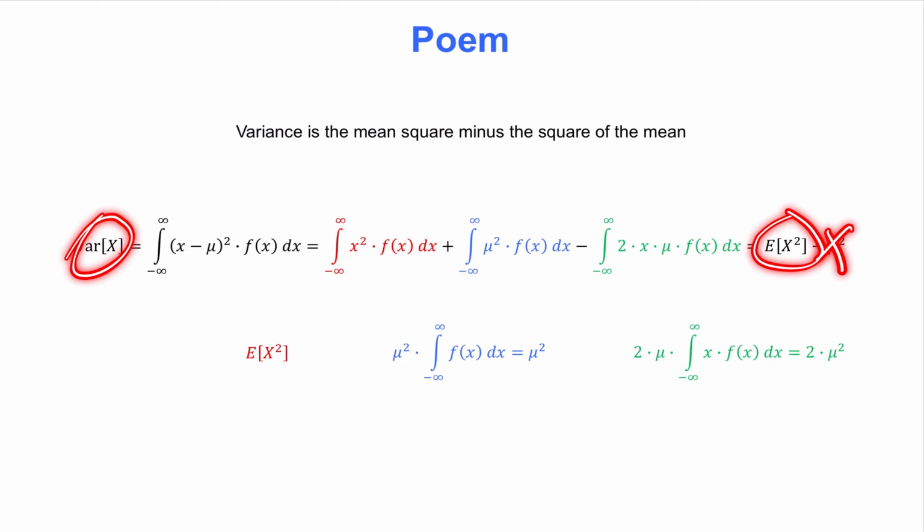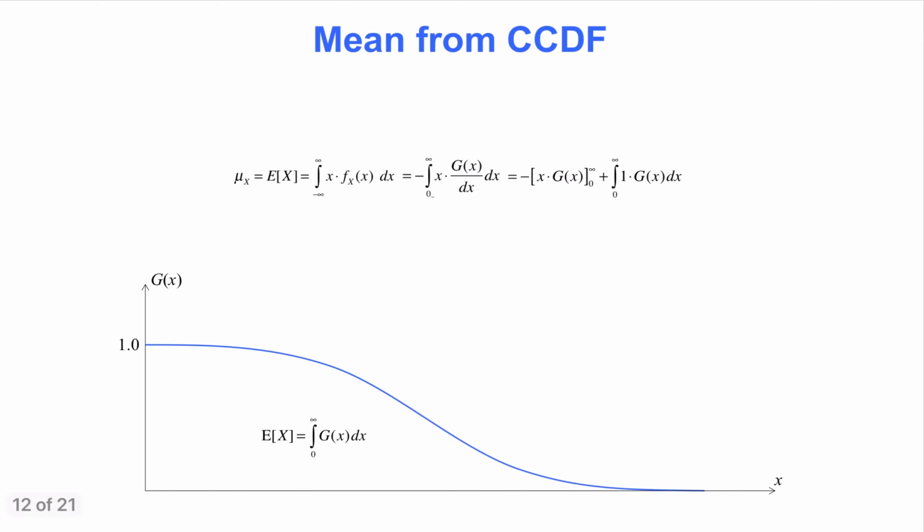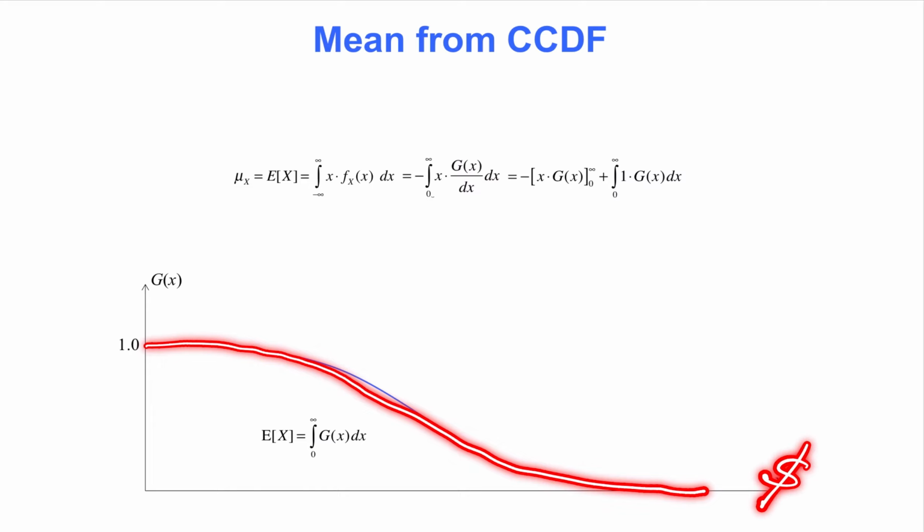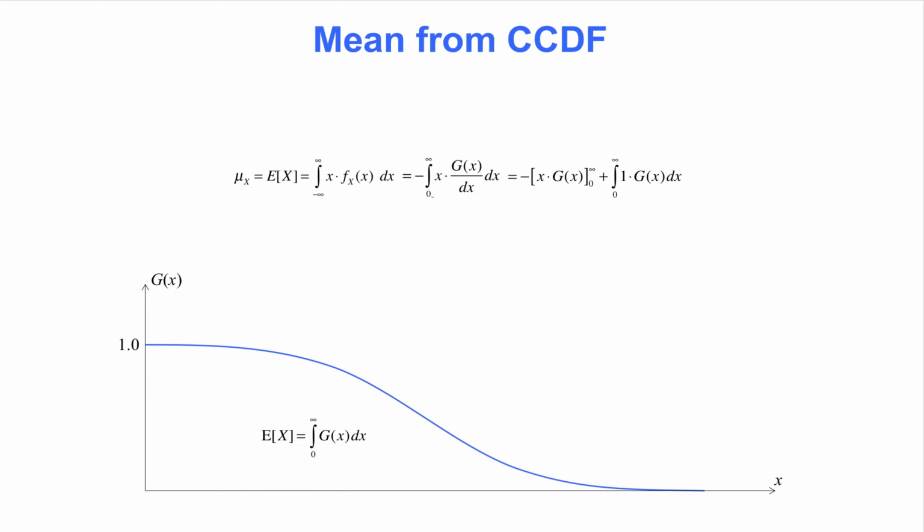On the next slide, we look at a technique that can sometimes be used to calculate the mean of a random variable. This is not about statistical inference using observed data, which is addressed in another video. Rather, this is a situation where we imagine that we have obtained the complementary CDF by some other analysis. This situation occurs in performance-based earthquake engineering, where the probability distribution of monetary loss caused by ground shaking is expressed by a complementary CDF. It is then called a loss curve.